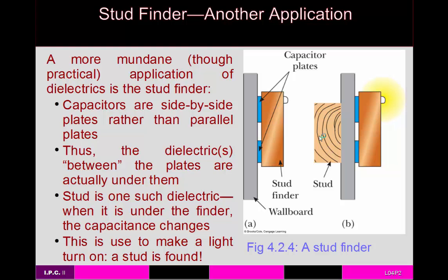And so one way of doing that, of course, is that you can sort of knock on the wall and listen to see if it sounds more hollow or more solid. And where it's more solid, that's where the studs actually are located.